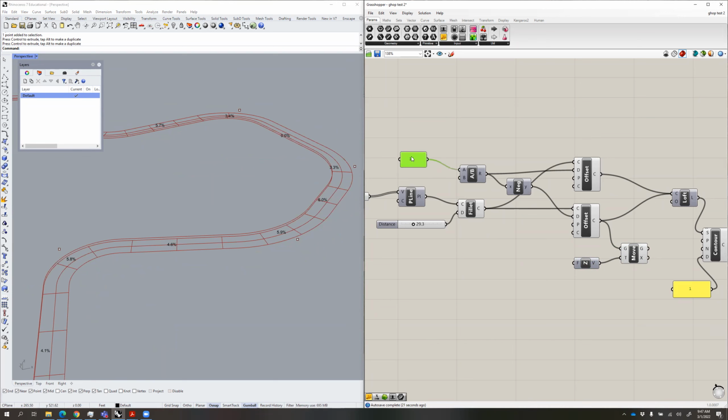along this 11-foot width path. So we want to take this number right here, this 11-foot width, and multiply that by the cross slope percentage, 0.02, right? 2% is the typical maximum cross slope for a walk. So we plug that in here, and now we've got a vertical change number that we can use. Actually, we're going to do a negative value because we want to move it down. So that number goes into here.